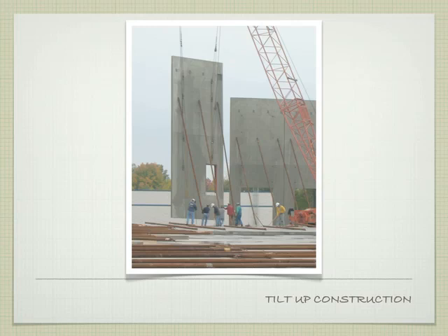Right, exactly. So in some cases, there's a bit of a footing that's poured around it that helps hold it in place. Sometimes there's a little bit of a keyway that's done. It varies a little bit in terms of how they do it. Sometimes there's a notch, and I have a video that we'll see a little bit later that you can see. Sometimes there's a notch where the surface slab here is a little bit higher, right? And then it goes down before the footing, and this fits down inside that notch, right? And then they'll pour a foundation against the outside to help hold it in place. But there aren't those dowels that go up through the building. Yeah.